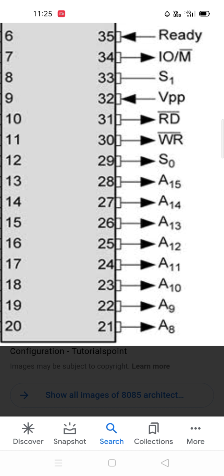Okay, now this is the address side. Address side is where it just gives out the address, but it never receives anything on these lines. Okay, it never receives from A8 to A15. Only it can send signals through that bus, and it cannot receive any signals from the bus. Okay, so that is why it is going out.